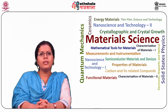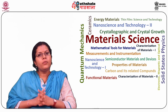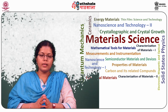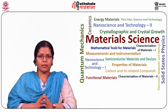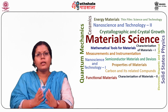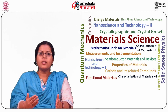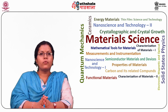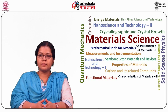Students, now let us consider the moving coil. The moving coil is wound with many turns of enameled or silk covered copper wire. The coil is mounted on a rectangular aluminum former which is pivoted on jeweled bearings. The coils move freely in the field of a permanent magnet.